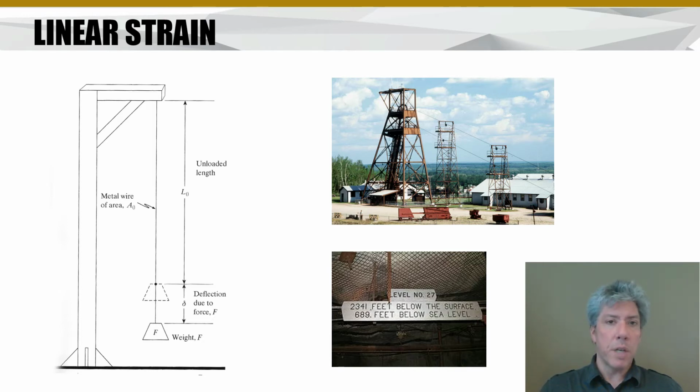Do you think it would stretch under load? Absolutely. Even though it's wire or steel rope, basically made of steel wire, it is absolutely going to stretch. An easy way to think about strain is to think of the unloaded length of the wire and then the deflection due to the force once you've got a lot of metal wire played out. The strain then would be that deflection delta divided by the original unloaded length.